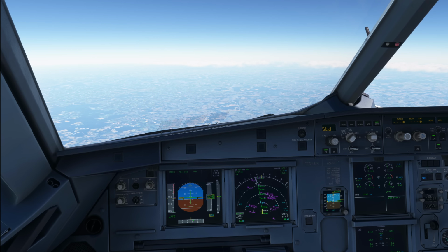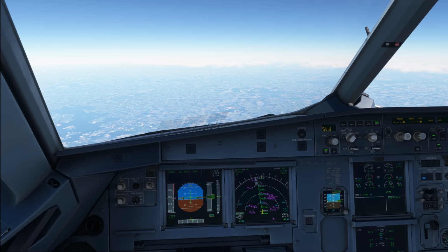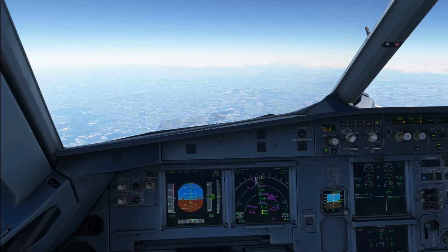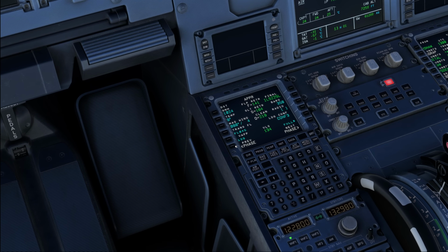On the takeoff performance page, if conditions and regulations permit, the flight crew should reduce the altitude for both the thrust reduction altitude and the acceleration altitude as much as is possible. Depending on regulations, the lowest authorized altitude may be 400 feet above the ground. So this is down here on the takeoff page, and on here, rather important, remember the standard noise abatement procedures.